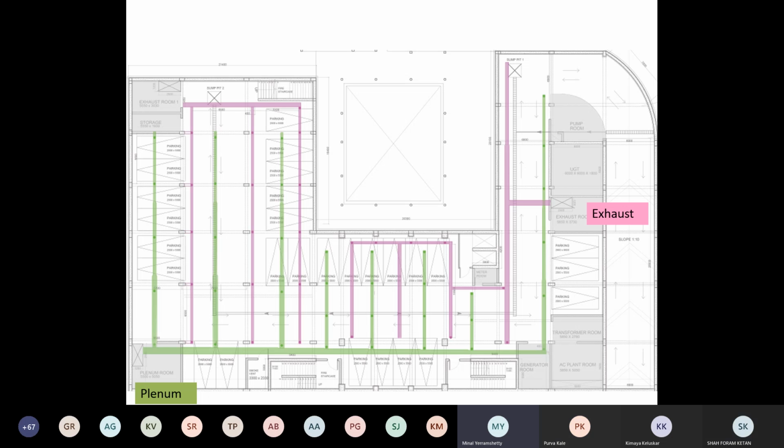So this is what your basement ventilation part should ideally be. You should have two rooms, depending on two rooms as and when your need be. As I said, if the pressure difference can move my air, I will try to cut down my cost and my maintenance and my space everywhere. So depending on the size, the requirement, and the program of your building, you will go for this kind of